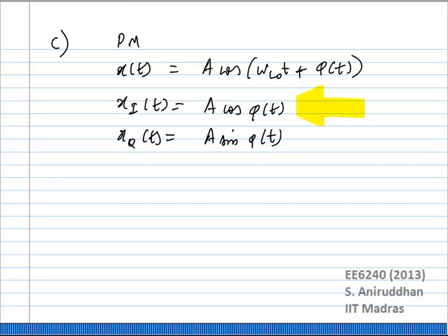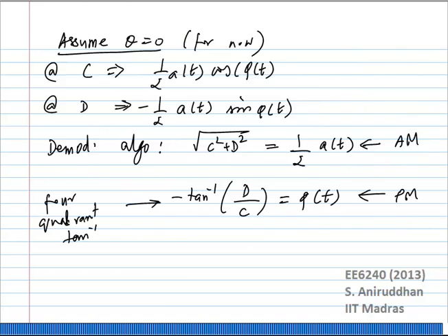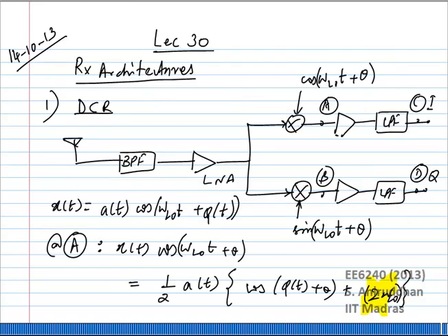Okay, so let us say you have a modern receiver and you have a phase shift theta between the LO and the RF. Does it cause a problem? Or not? No problem. Okay, so he says no problem. If theta is 90, correct.